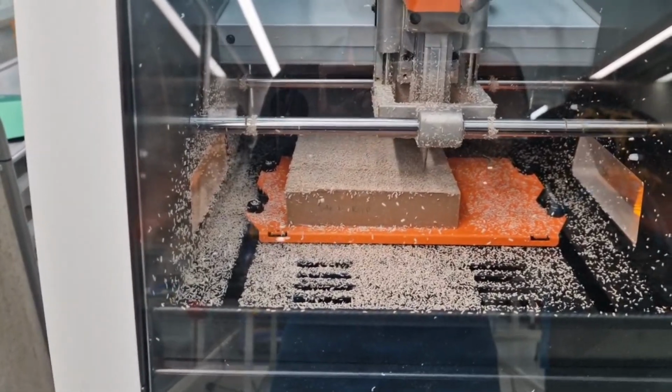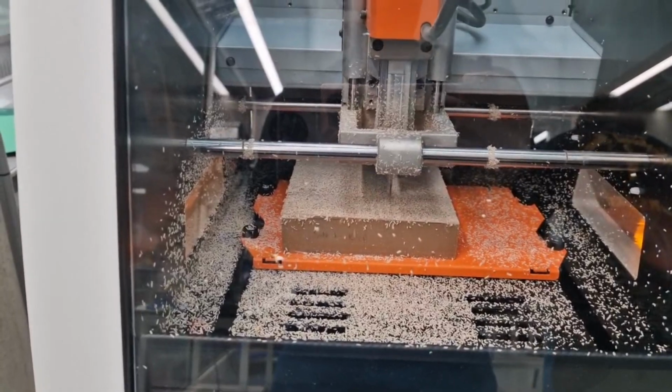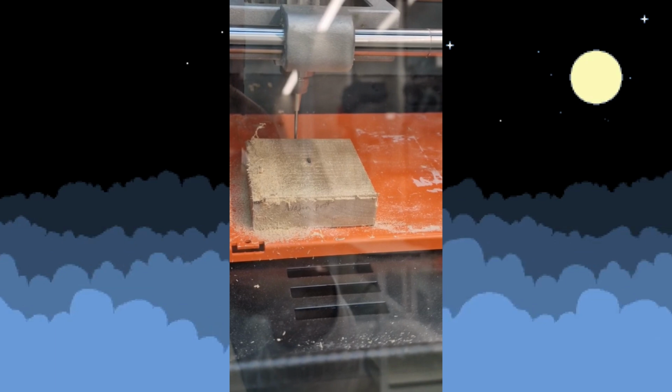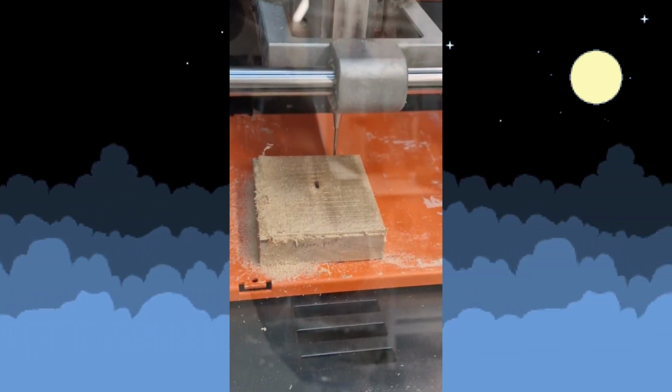the material type. For example, when jelutong was used, using double-sided tape worked perfectly fine as the wood chips made were less refined and thus couldn't get underneath the double-sided tape layer. However, when using plywood, as the chips produced were more refined, it was easy to intercept the double-sided tape layer and declamp the stock from the CNC bed.